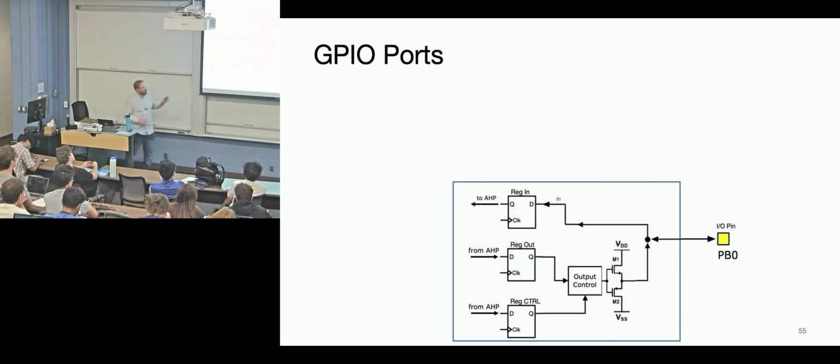We talked before about the anatomy of a GPIO pin. We drew it out, and we looked at the details of the actual one in your data sheet. But the idea here is typical. There are multiple registers in a peripheral. In this example, we have three registers: an input register, an output register, and a control register. The control register is changing the function of the pin between an output or an input in this toy example.